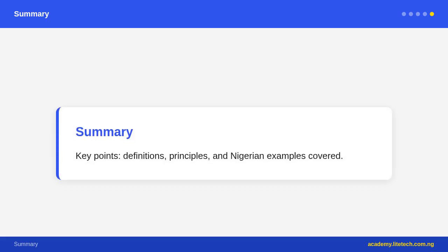Velocity ratio, also called the pulley ratio, in belt and pulley systems determines speed changes. If a small driving pulley of 100 mm diameter drives a large pulley of 400 mm diameter, the large pulley rotates at 1/4 the speed of the small one, but with 4 times the torque. This is used in fan drives, lathe drives, and conveyor belts.